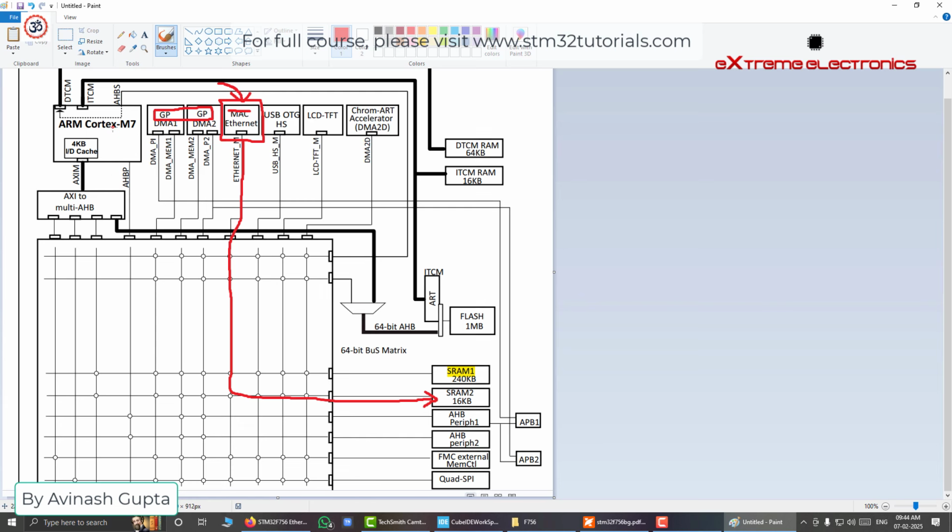It is free to communicate simultaneously. At the same time, the CPU is able to access this SRAM through this channel. You can see our CPU can access this RAM. So this data flow will be completely parallel to this operation of the CPU, and it will not hinder the data flow done by the CPU. For this reason, they have split the RAM into two parts to allow true concurrent access through this DMA.